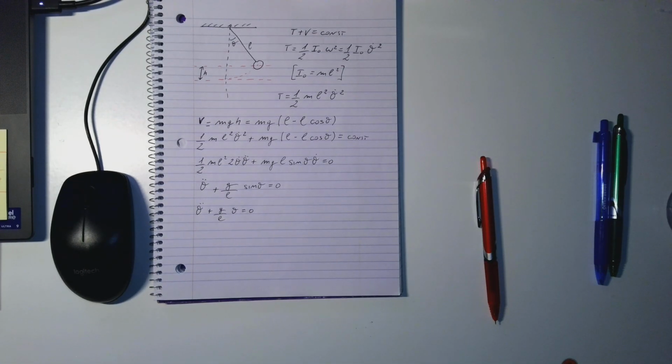Is this familiar? Yes, because it is exactly the same equation that we obtained when we were using the forces, the first time, to find the equation of motion. Which means that, of course, in this case, the natural frequency of the system is going to be the same, the response of the system is going to be the same. If we use the same initial conditions, of course we will have the same particular solution and the same response. Makes sense?